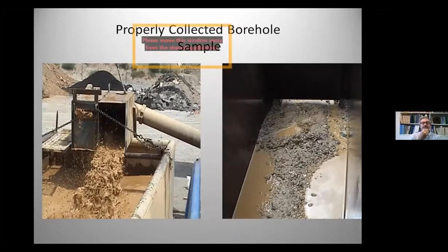But whenever there's a change in the drilling tubing, you can temporarily stop the drilling circulation system, and now you can get a first-hand sample of the interval that the drill bit just passed. So for every 3 meters, or 6 meters of penetration, you can then get a sum total of the materials that it just passed through. So this gives you your first idea of what kind of materials you're drilling in.